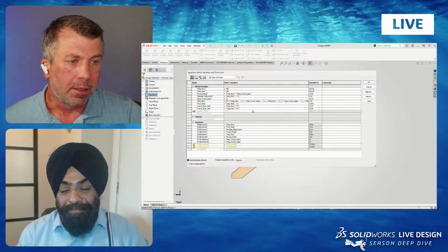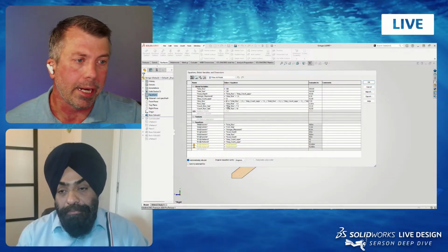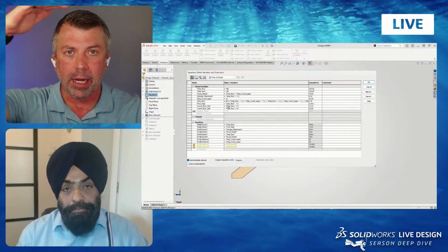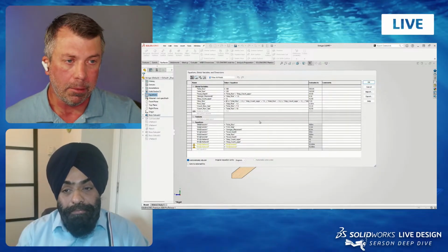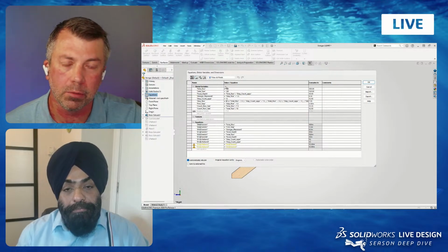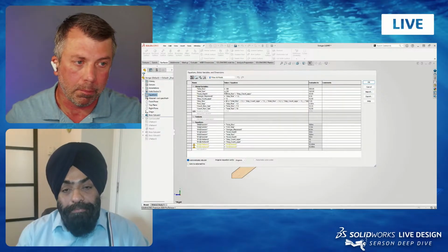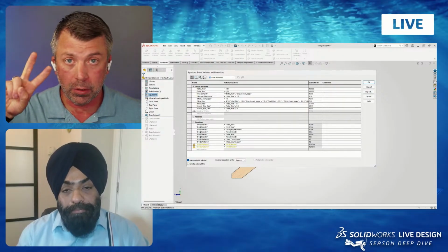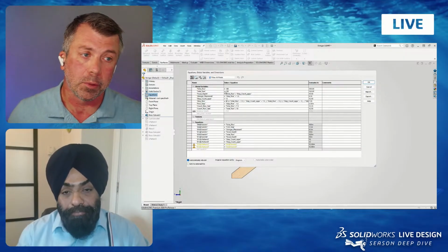Yeah. So here's a great example. I couldn't figure out why my steps or my rise were going outside of code. That's because of my input values, total rise and total run, so I can go measure at a house, we know how high it has to be, and figure out whether it can fit in those parameters. Those are my two driving variables. The other option I could switch to is saying how many steps we want.